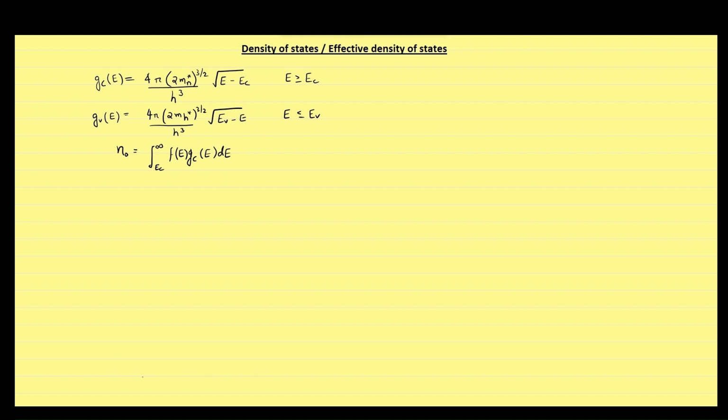where G(E) dE is the density of states in the integral energy range E, and n0 represents that electron concentration is considered at the equilibrium condition, meaning the electron concentration does not change. Also, F(E) is representing Fermi Dirac probability function.